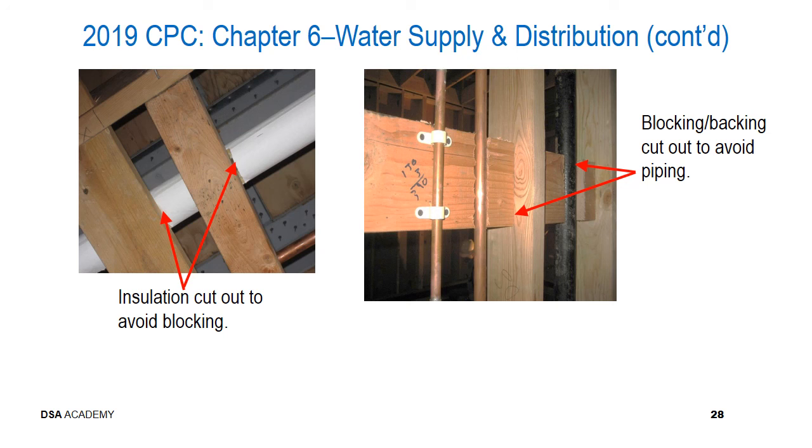You can see in the foreground there's a copper water pipe, and in the background is a cast iron, either a vent or a waste line. And again, this can be a common occurrence, and it's got to be corrected before the product inspector will sign off for this installation.